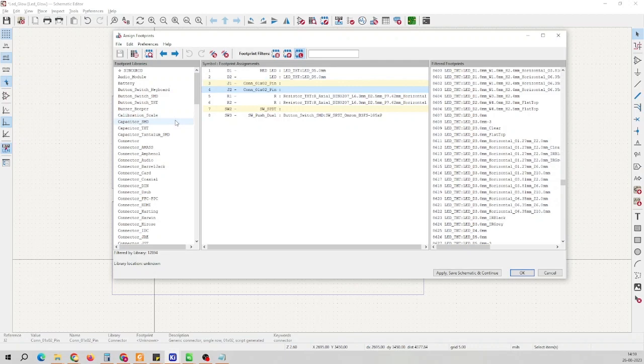So we are now planning to select a connector which is easily available in the market and which we can easily use. Normally, as you know, your phone connects via Type C, Lightning port, or a micro connector. Those types of connectors are easily available in the market, but soldering those components is very difficult. Just for the beginning part, we don't want to introduce any complication in terms of soldering. So we are now going to use some other kind of connectors which are through hole in nature and which are easy to solder and work with.